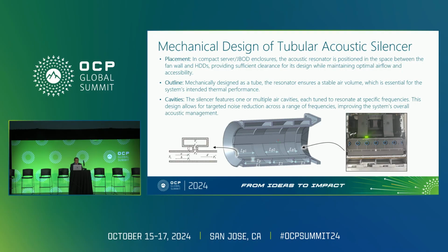To achieve this, the acoustical resonator is strategically positioned in the gap between the fan wall and the HDD. The placement is crucial as it allows for sufficient clearance for the silencer's design, while also ensuring that the airflow remains unobstructed and the HDDs remain easily accessible for maintenance.